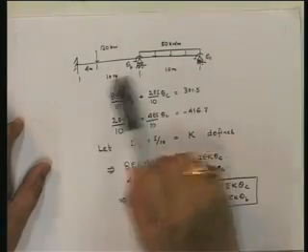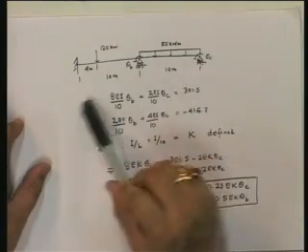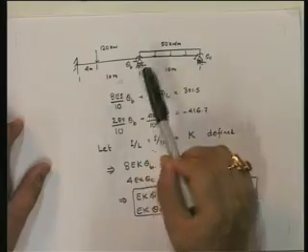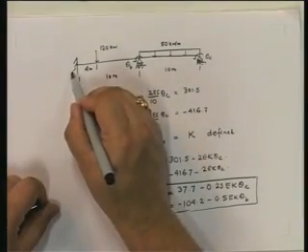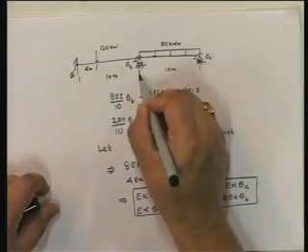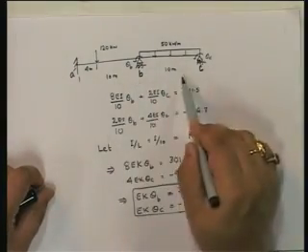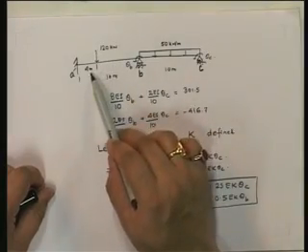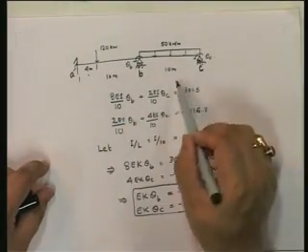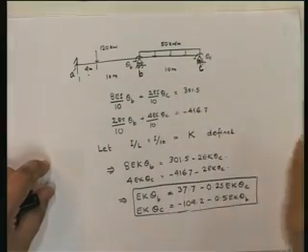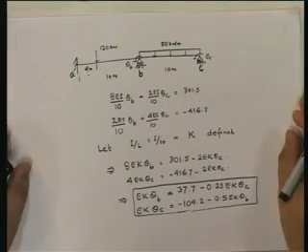For that, I am going to take a problem that I have already discussed earlier. This is the beam problem. Do you remember, these are 10 meter spans, fixed at A. I'm going to call this A, this is B, and this is C, each 10 meters long. This one has a 120 kilonewton load at 4 meters, and over BC you have a 50 kilonewton per meter uniformly distributed load.